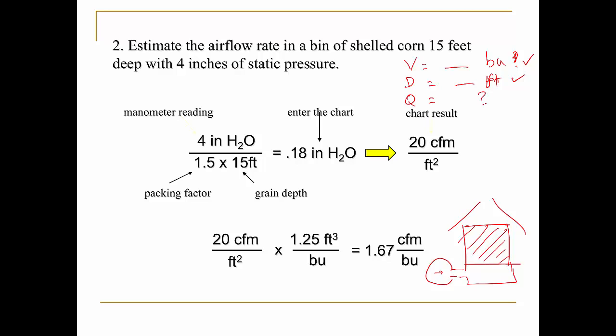To determine the flow rate, it's a bit hard. You need to have a pitot tube. You need to traverse through, but actually here there is a disturbance. It doesn't work very well. And trying to measure the velocity there, it is a challenge.